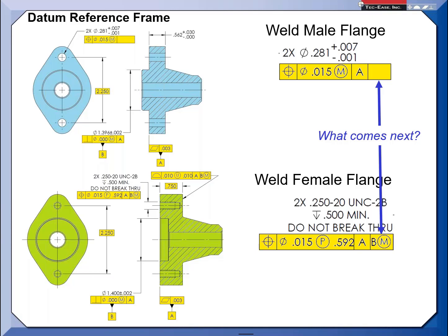So there are pros and cons, and again, it goes back to engineering and design intent. Just by you guys asking questions, I can come up with some great examples of, oh, I don't want it to shift in this case, so we would not add modifiers on your datums. For example, I used to work with missiles, and on some of the missile joints, we'd put in 2 dowel pins that would fit the missile joint, and the bolts were just for clamping. The key locators were the dowel pins. If I put modifiers on those dowel pins, they could shift and move. In other words, the outside diameters of the missiles could shift, and they wouldn't stay very coaxial. My aerodynamicists hated when the surface might protrude proud on one side, because it caused drag. So design intent is what I'm alluding to, for why you would do these. In this case here, it was no big deal. We took advantage of shift, possibly, FYI.